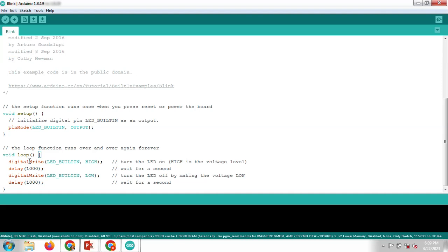So whenever we are assigned a task, we can identify whether that particular pin works as an input or an output. If it is an input, it works as a digitalRead, and if it is an output, it works as a digitalWrite. Here we see digitalWrite, because the pinMode LED is working as an output. And if the sensor is analog, then we write analogWrite or analogRead, replacing the word digital by analog.